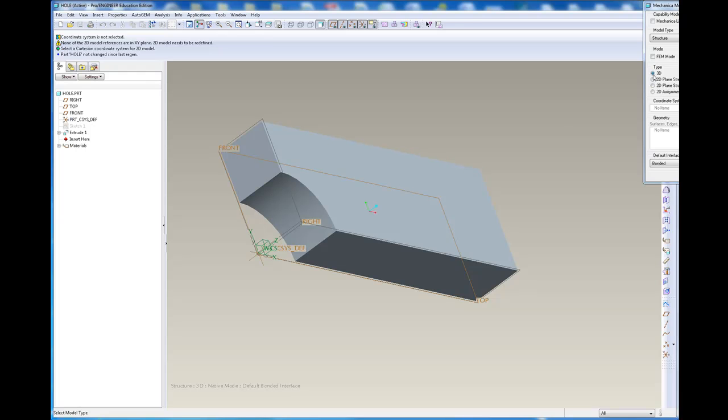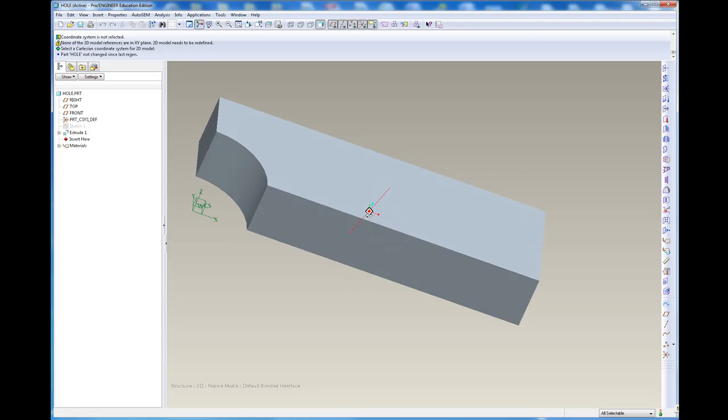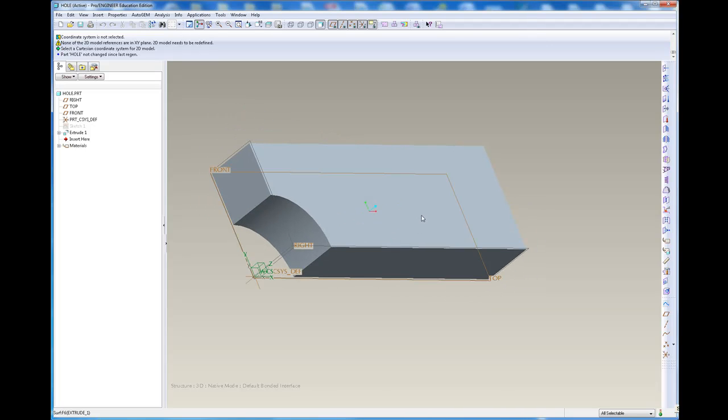Right now it is a 3D model, and that's what I'm going to want to be working with, so I'm going to go ahead and cancel and keep that as a 3D model. Now, as compared to the picture from the stress concentration chart A15-2, I've created a quarter model, and I think that is going to be sufficient. What I need to do is constrain the model, load the model, assign material properties, all of those kinds of things. So first thing I'm going to do is constrain this surface, and I can actually pre-select the surface.